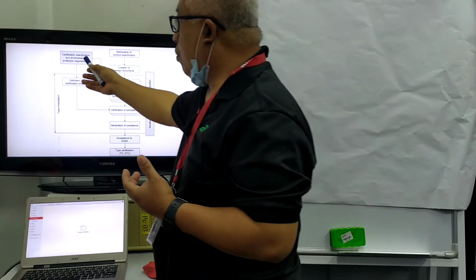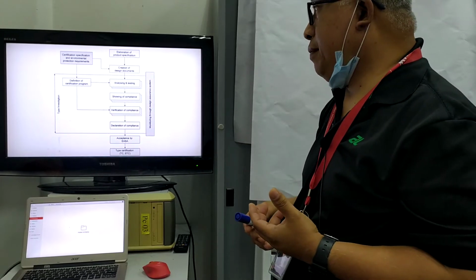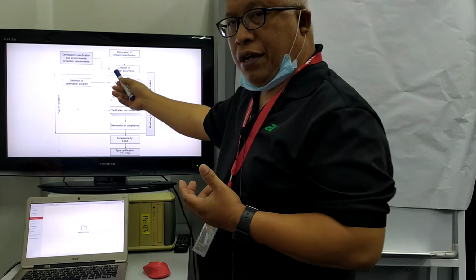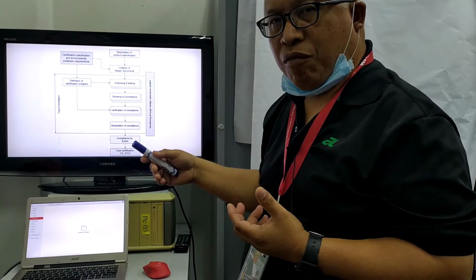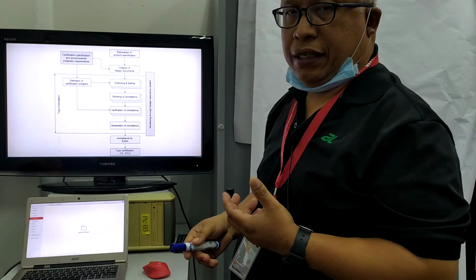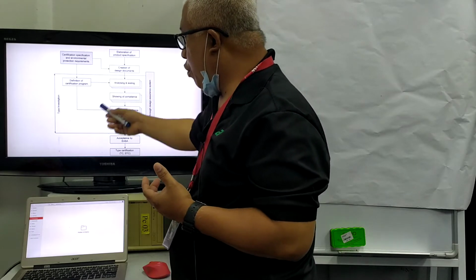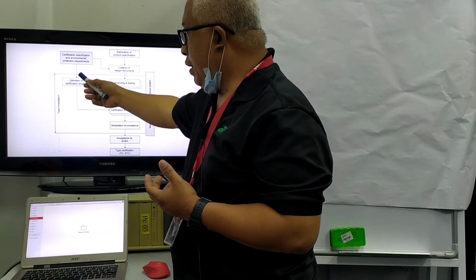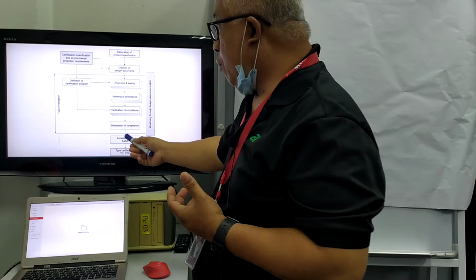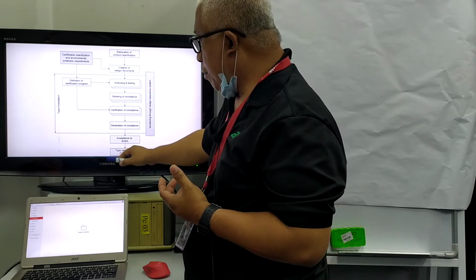After you get the product spec, you decide or negotiate with the authority on the certification basis, how the product will be certified. Then you go for the detailed design. After you have the detailed design, you have to show compliance to each paragraph or requirement, by analysis or testing, and then someone will verify each compliance. Along the way, during the showing of compliance or on the design requirements, the FAA or CAM will be involved and take part, for example approving the test plan, witnessing the test report, and reviewing your design. Once everything is satisfied, all the design requirements have been complied with, shown, and verified, that is where you will get the type certificate.